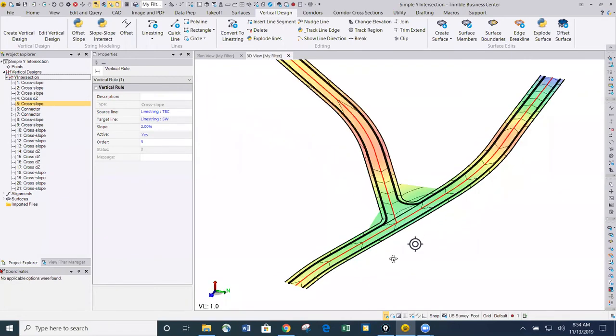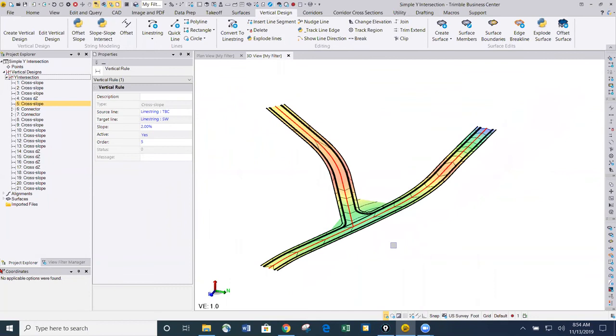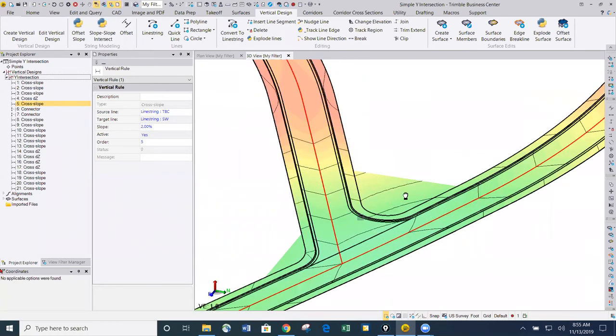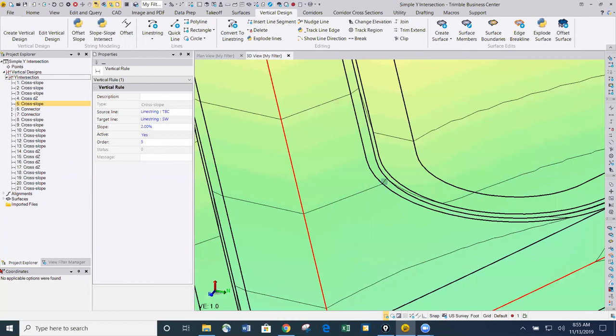We do have a couple of questions here that I haven't been able to answer yet, and hopefully you can show them. Okay. Number one, can you show an example of how to tie in utility networks such as storm inlets as low points in the road to ensure drainage? Yeah, so if you know where there's a storm inlet in here, then you would just add an elevation control for the inlet. So for instance, again, not knowing the elevation, but we could just go into the vertical design here, edit this.